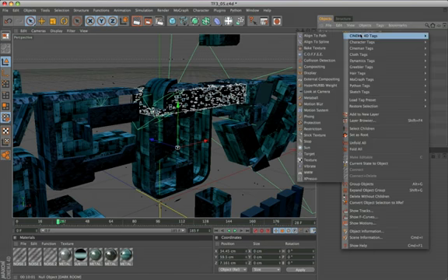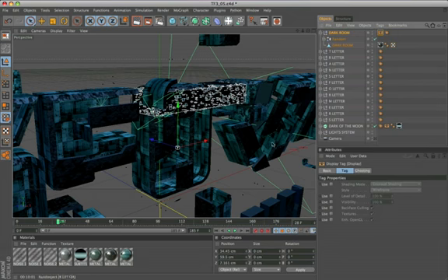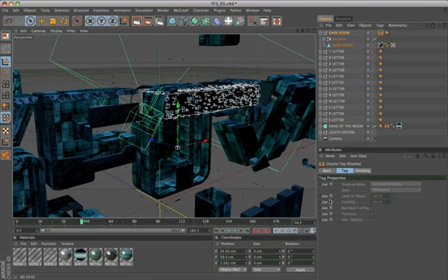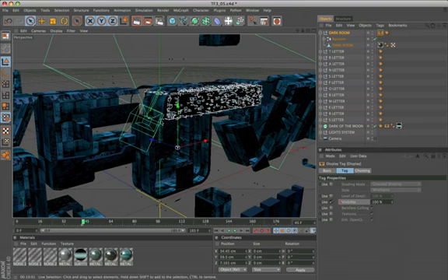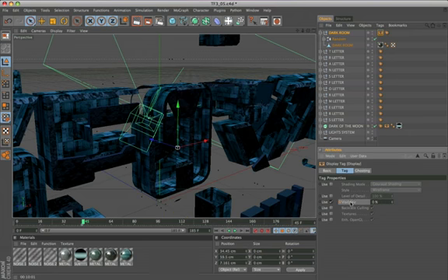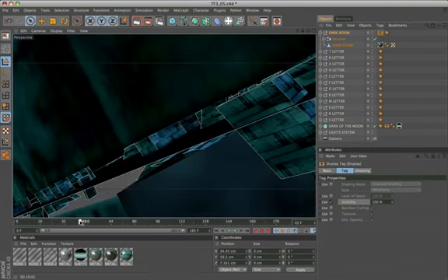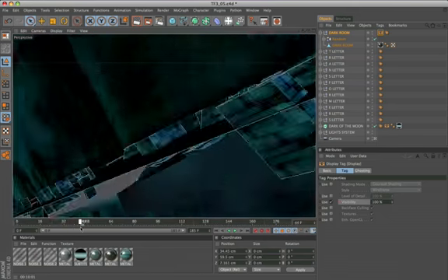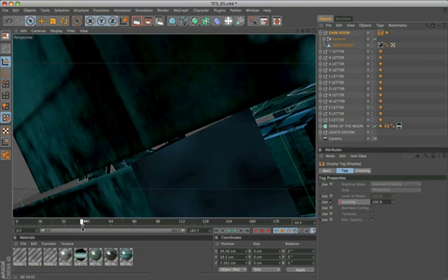OK, to complete, add the display tag to the darkroom layer and activate visibility: in frame 44 the value 100, and in frame 45 the value 0. In this way, after the closing of the door layer, the entire darkroom block will not be visible in our animation. Strategic.